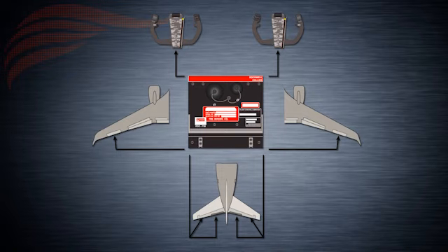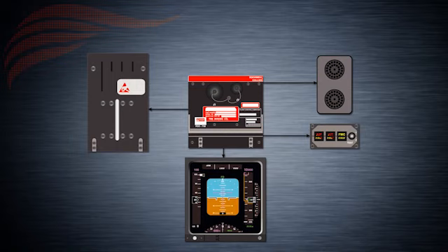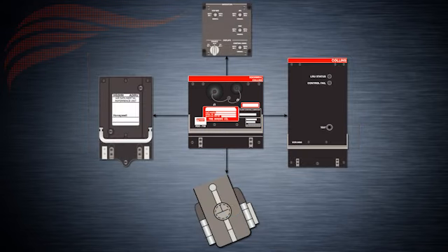Under Auto Flight Control Column and Control Surface Movement, we have Control Column Force Transducers, Aileron and Elevator Actuators, Stabilizer Trim Electric Actuator, and Mach Trim Actuator. Under Displays and Warnings, we have the Common Display System, Aural Warning Module, Autoflight Status Annunciator, and Remote Electronic Unit. Under Sensors, we have Control Position Sensors, Switches, Nav Sensors, and the Air Data Inertial Reference Unit, or ADIRU.